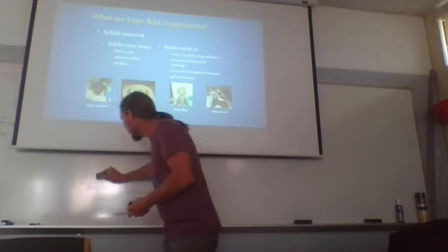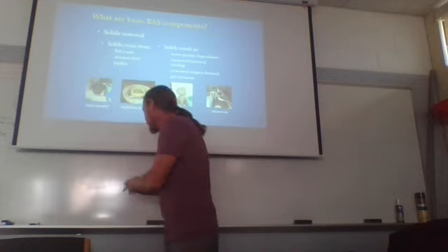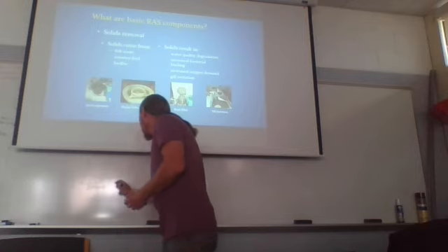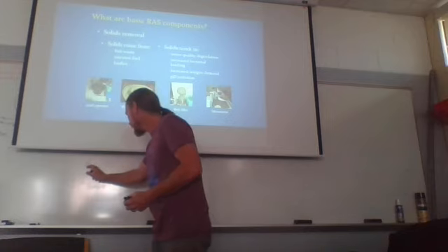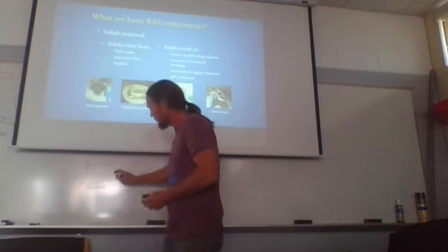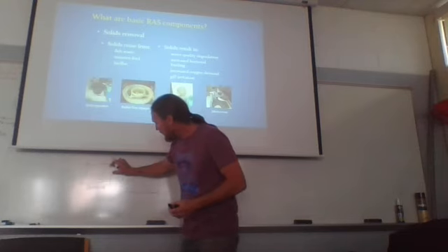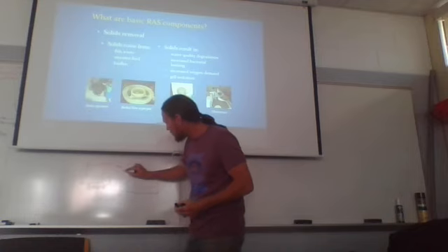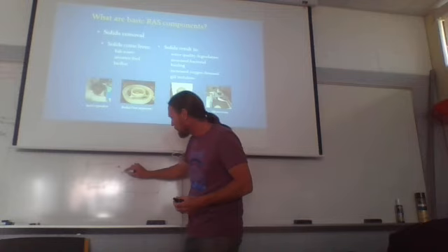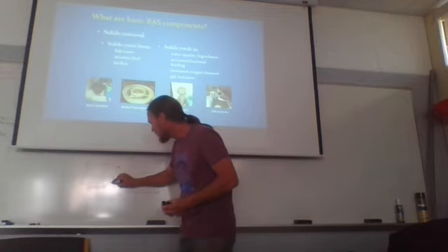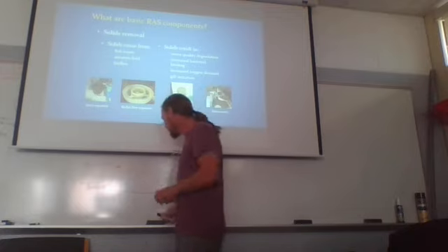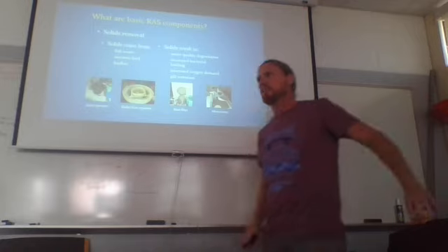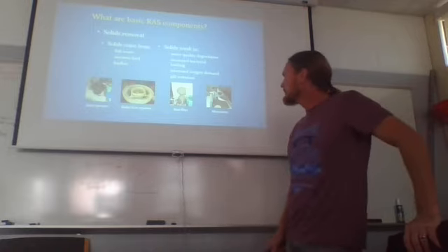I've seen other ones where the baffles are oriented like this, and so the water's coming in here, and it's flowing across, and as the water moves up, it's getting confined into smaller and smaller space, so the velocity picks up a little bit, and then there's a sudden drop in velocity when it gets to the other side of this baffle, and that sudden slowing down causes a lot of particles to sink to the bottom, and it does this several times. I don't know what the name of that one is, but I've seen it multiple times. Plate settler or something like that.